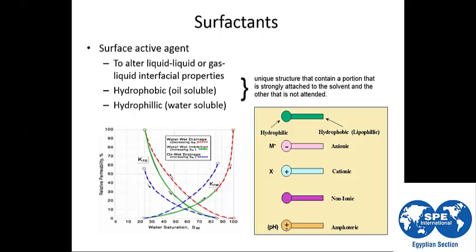To keep this foam stable and avoid the escape of nitrogen from the gelling agent, because we are pumping the gelling agent in combination with the nitrogen to create a foamed fluid, we are using the surfactant.